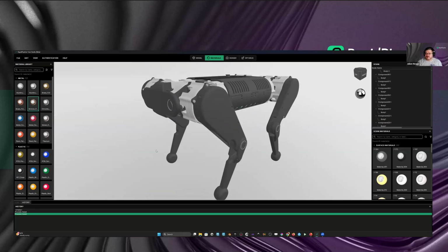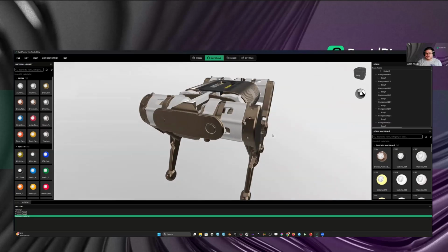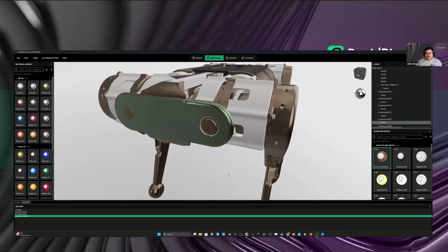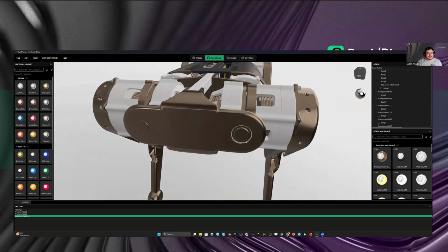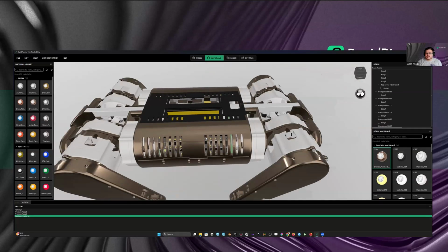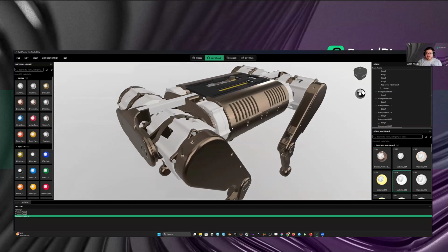And the cool thing is what you can do here on the fly: you can just drag and drop a material and replace a CAD material with it, and it will replace the whole material tree for all these models and parts. And you can see that this material technically has a texture, it has a roughness map, everything with it, but it's not really reflected on this model. And of course, the reason is that we don't have UVs assigned, but that's actually pretty easy.